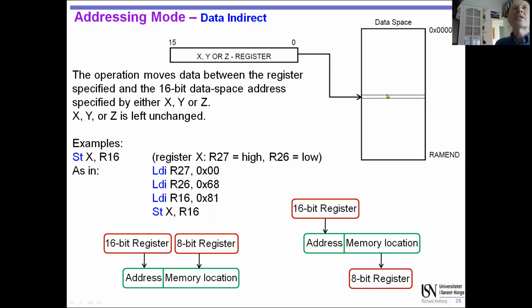there is some data. And if we're going to get data from, so this is then saying, okay, point to that location and get what's in that location, store that in an 8-bit register. And this is saying, take the value that's in that location as a destination, and take another 8-bit register and put the value there in. So this is going from register to memory, but just the memory is indirectly addressed. And this is going from memory to register, but again, it's indirectly addressed. That gets a bit more complicated and needs a bit more reading through.